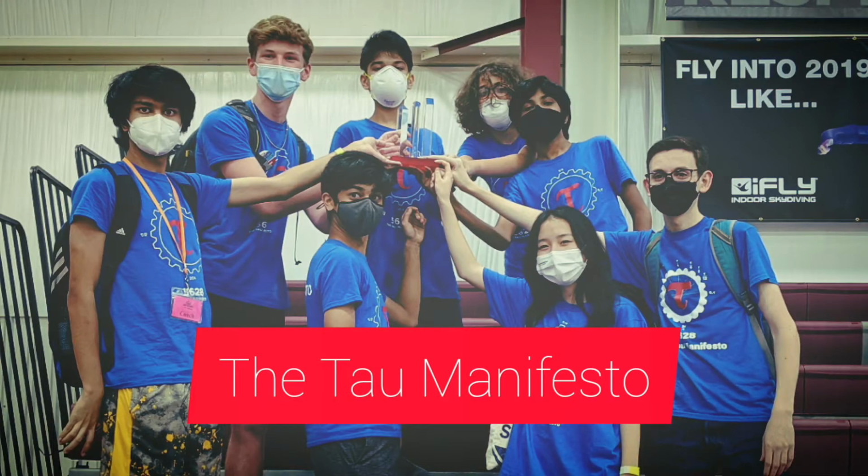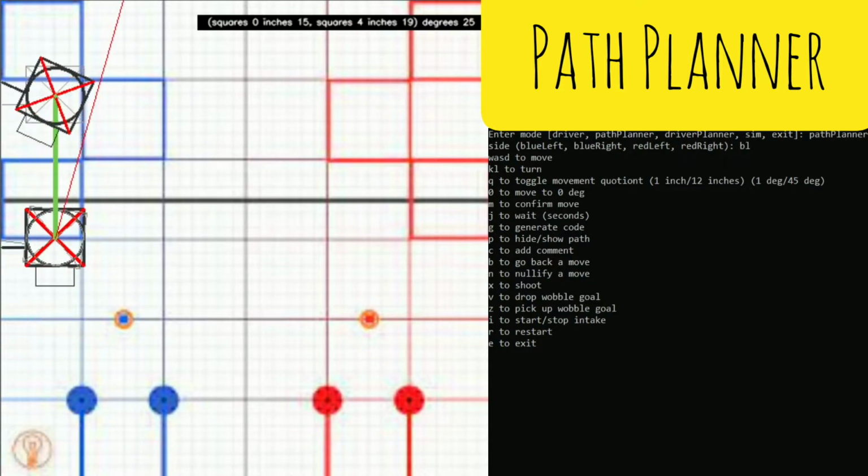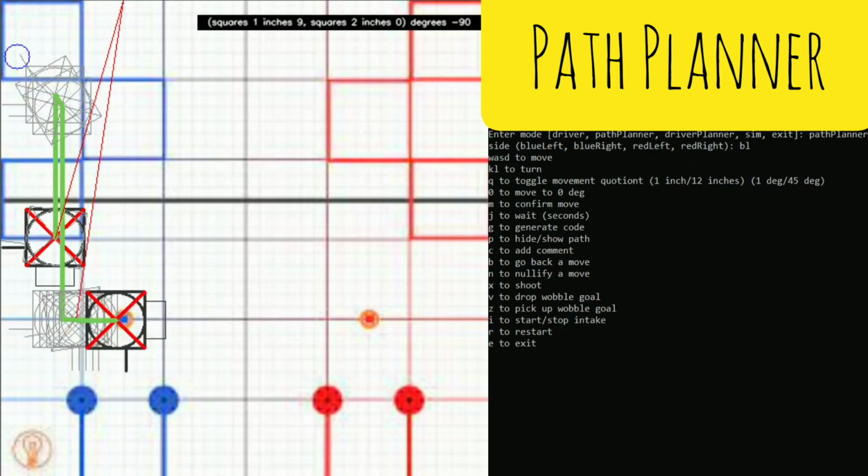This year, our team went above and beyond to push the limits of autonomous programming, exploring exciting and unique solutions. We created and developed a Python application from scratch that we call a path planner, which allows the user to lead a virtual robot through a set of movements, which is then used to automatically generate code. The program achieves this by providing the user an interface to perform actions such as move the robot, automatically shoot rings by calculating RPM and angle, and manipulate wobble goals.